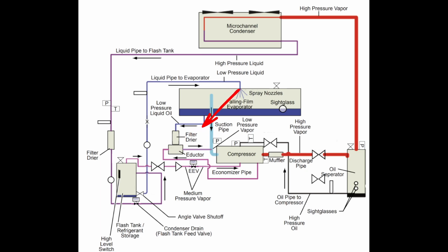And then we've got our oil recovery port coming off of the evaporator. And this evaporator maintains a really low level of liquid. It's not very much. So this eductor line is actually really low on the evaporator. But we're pulling that oil latent liquid refrigerant off, and this particular machine flows that liquid through a filter dryer.